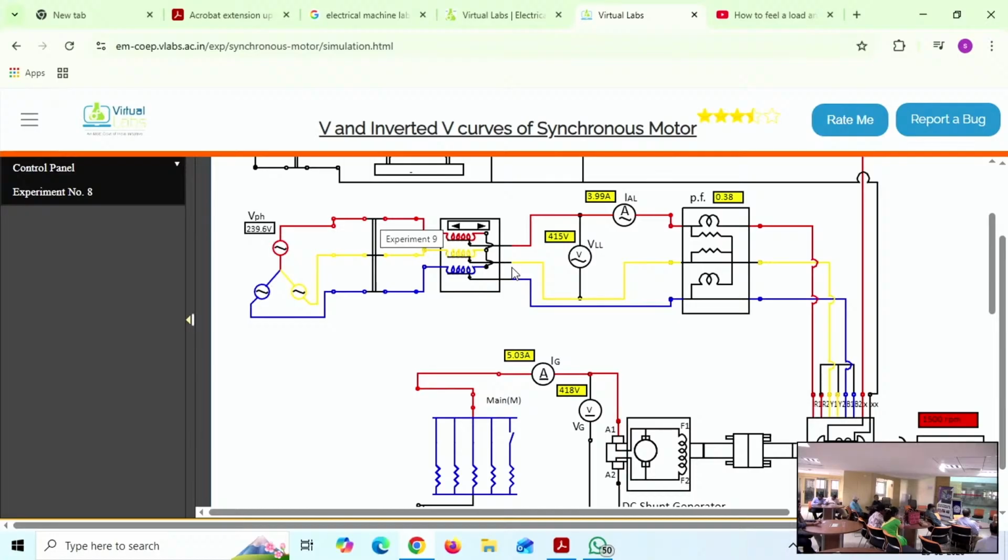Directly, can we give? We can give, but it is not suggested. In case of an induction motor, we should not give. Three-phase induction motors are self-starting, but we first need to reduce the current. If you directly close this switch at 400 volts, that is practically not suggestible. Safety is ensured first. For a 3-phase induction motor, a starter is compulsory, and DC motors also we have started.